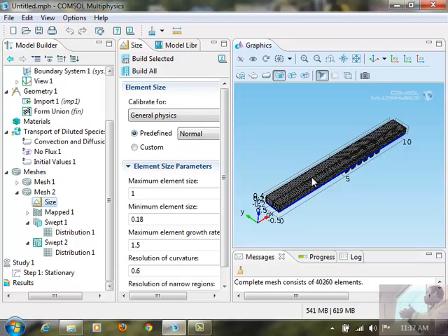Right. So if you have a groove on the other side of the rectangular domain, can you do this kind of treatment to sweep? Identical grooves on the other side? In principle, you should be able to, but according to their rule, you won't be able to. Then what I will do is make a mid plane in the rectangular domain, make that my source face, and then generate both upside and downside using that source mesh. Or use these two top and bottom faces and divide this rectangular domain in half. But you need to have a conformal mesh, and if you do that, it will not be conformal.